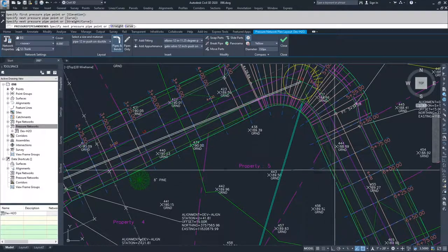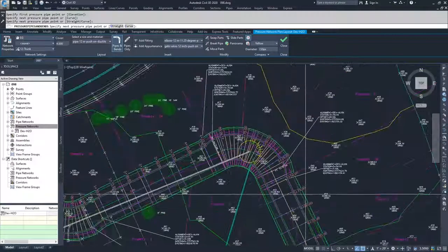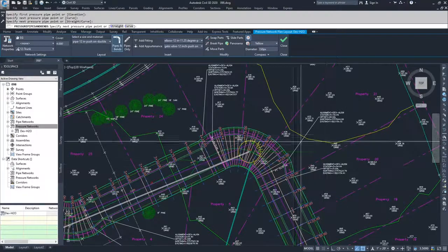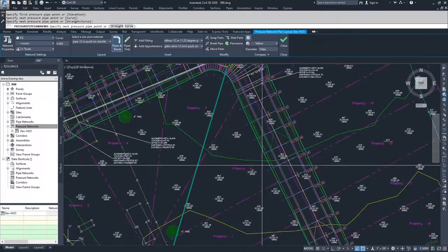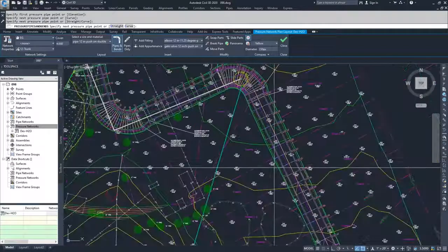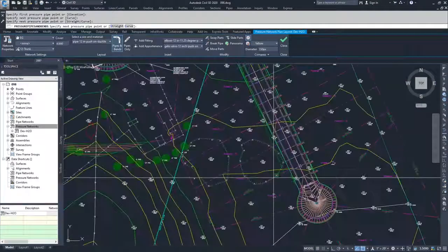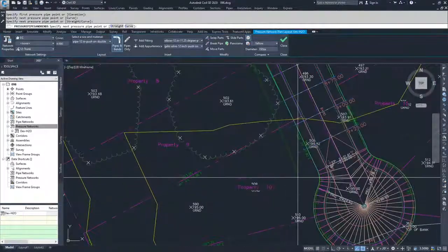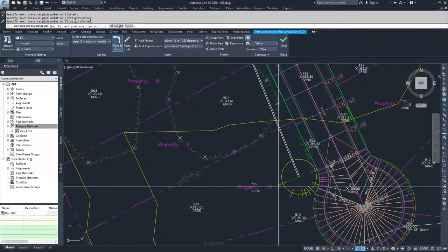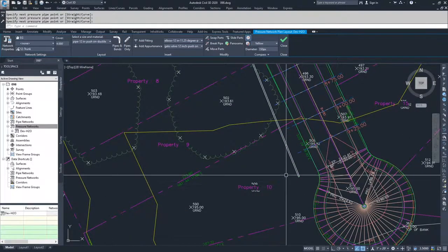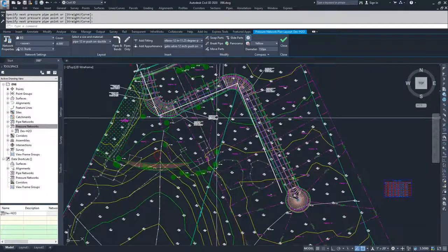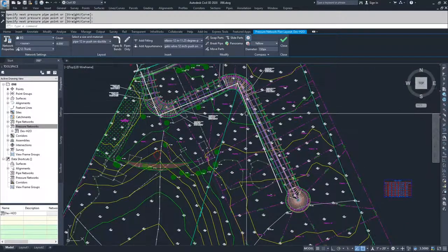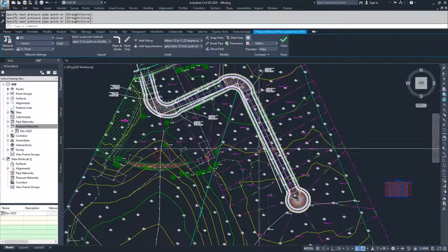And as you can see, I have the compass again. I don't want to be going this way, so none of these other bends are going to work for me. I have to go with this 90. But the problem is that this alignment isn't perfectly 90 in the corners, and so you'll see my pipe is coming way out over here. If I hit enter to close out of that command, I don't want to move these pipes around to try and get this to function better.